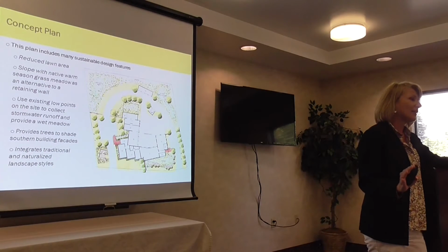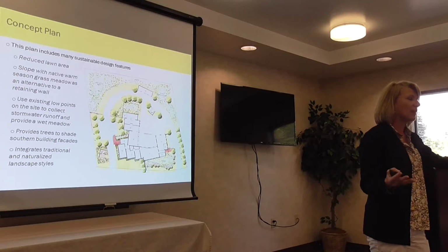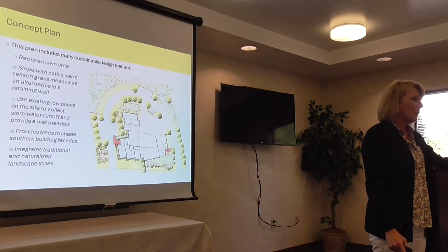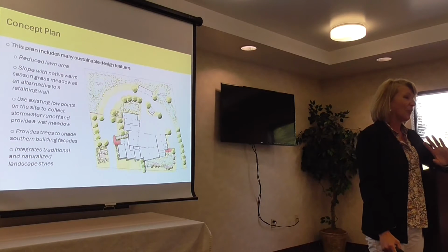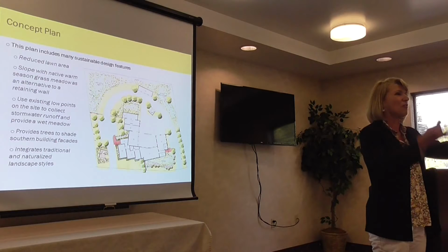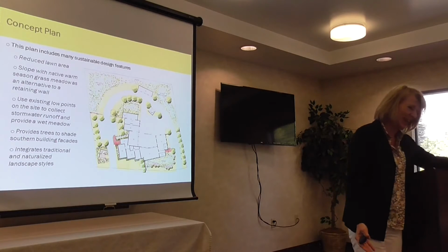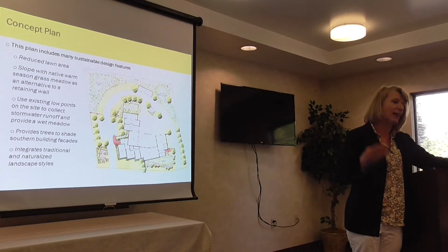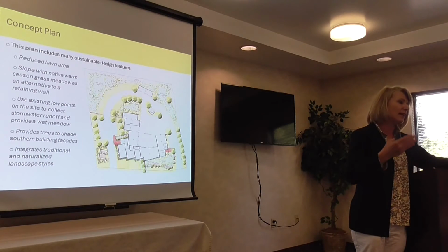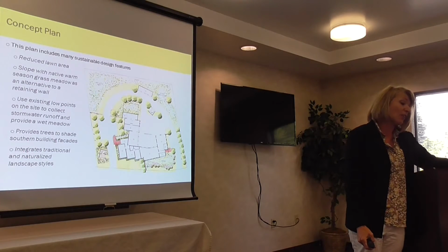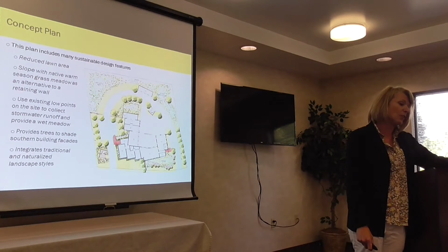In other cases, I see absolutely crazy stuff with retaining walls used basically to establish whether they can even build the project or not, because they need a retaining wall to get enough volume for their stormwater management. So looking at ways that you can establish some slope and get it stabilized reduces cost overall if you can reduce the use of retaining walls wherever possible.